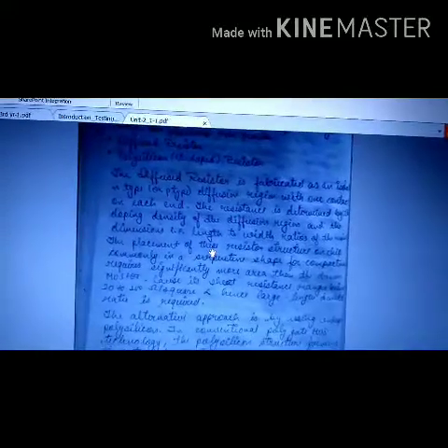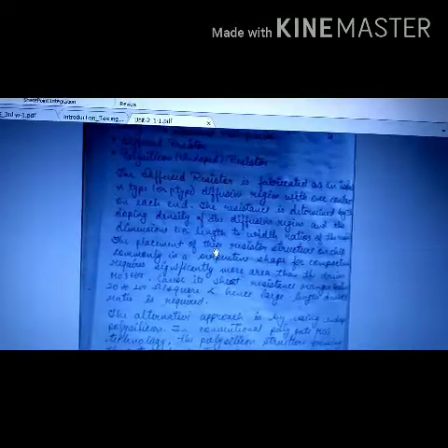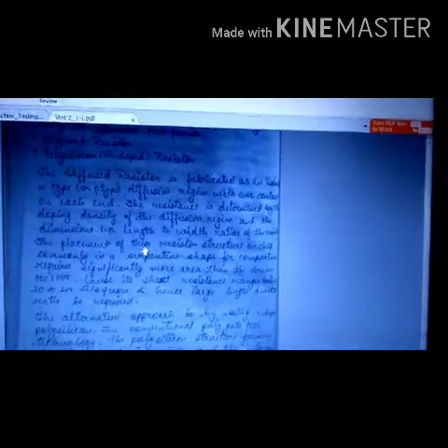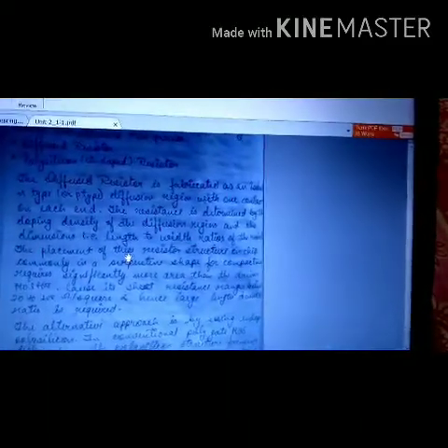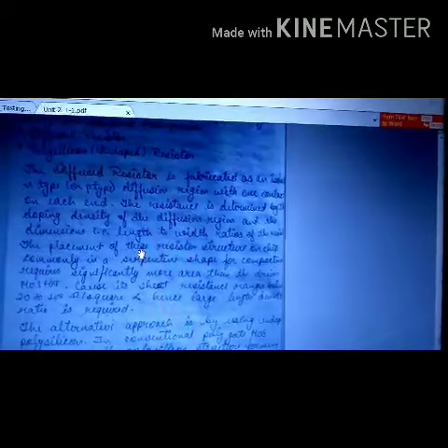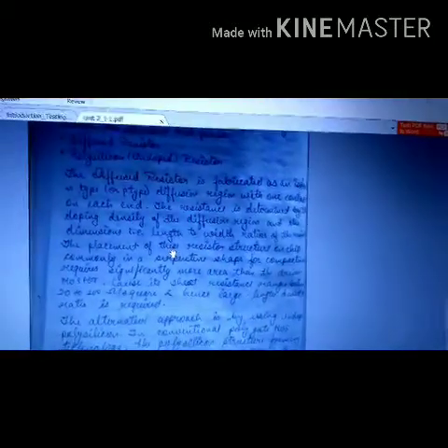Sheet resistance values are very small, so if we require larger resistance values, as we have seen in the previous graphs, in the lecture discussed on the VTC, we were using 10 kilo ohm resistors. So if our sheet resistance is 20 to 100 ohm per square, you can assume how much length it will take to get a 10k resistance.